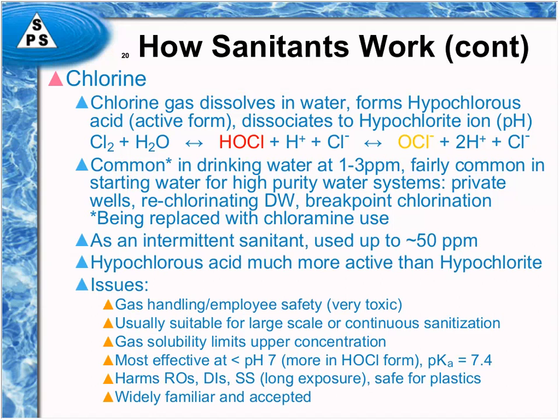Then there are also all kinds of issues associated with handling chlorine gas, not the least of which is its toxicity. It's usually only used when there are large-scale chlorination events going on, where you would actually get a railroad car full of chlorine gas and hook it up for use in large volumes of water, which often happens at water treatment companies, but doesn't happen all that often with pharmaceutical companies. And you can see what some of the issues are there. Chlorine will harm the RO membranes, DI beds, and stainless steel if it's exposed to it for a long time, but it is safe for plastics.